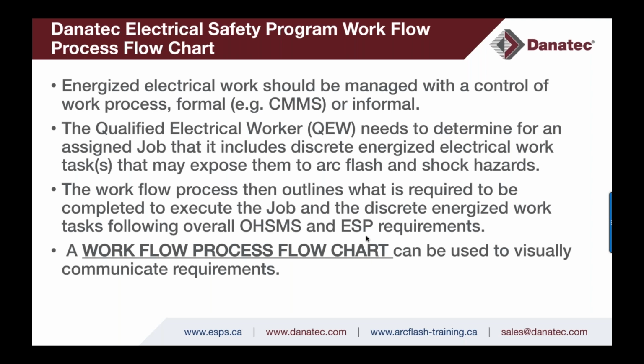And as far as how they manage the processing of that work, there's a workflow process that I've identified, and what you're going to see is the workflow process specific to the 2018 NFPA 70E and Z462, as well as occupational health and safety management systems or work control systems for large industrial establishments. So again, we have a job assigned to a worker. If, for instance, a motor's not running, then there'll be discrete energized electrical work tasks related to the qualified electrical worker troubleshooting that motor and, again, getting it back into service.